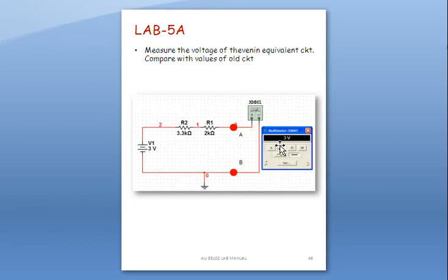And then, using theoretical values or Thevenin reduction methods, you will calculate. We have calculated 3 volts and 5.333 kilo ohms. And in real circuits, we cannot find the exact values, but we can find approximate values, approximate value components. And we will use a 3 volt voltage source. I will use two 1.5 volt batteries connected in series. And you will draw this equivalent.